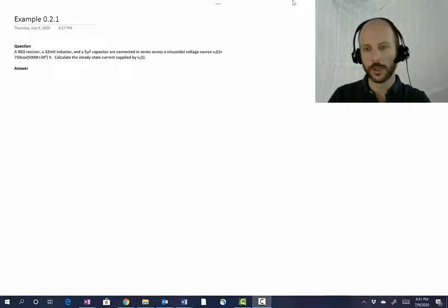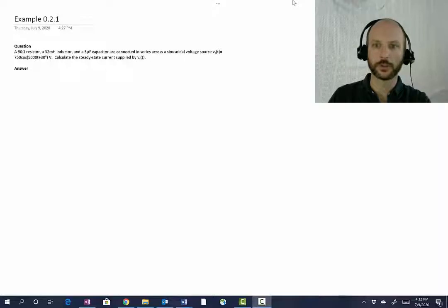It's the first and only example video in chapter 0, and it basically just builds on some prerequisite knowledge that you would have learned in earlier AC or power courses. We'll always start these video examples by restating the question exactly as it appears in the textbook. In this case, the question statement was: a 90 ohm resistor, a 32 millihenry inductor, and a 5 microfarad capacitor are connected in series across a sinusoidal voltage source. The voltage source is Vs of t equals 750 cosine of 5000 t plus 30 degrees volts. Calculate the steady state current supplied by Vs of t.